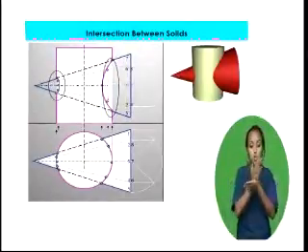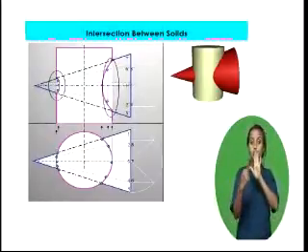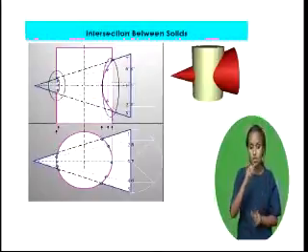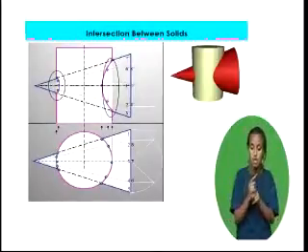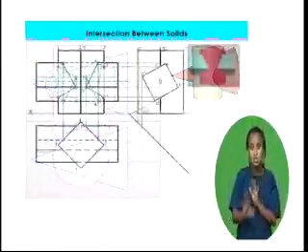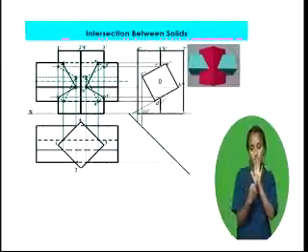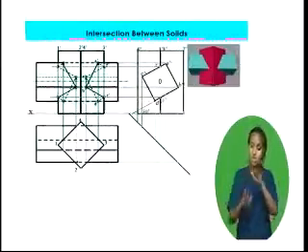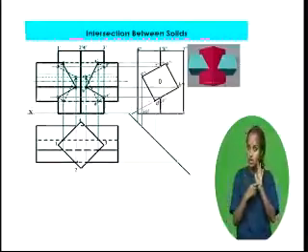On a sheet metal drawing, however, a sufficient number of points must be located to obtain an accurate line of intersection and an ultimately accurate development. The line of intersection of two surfaces is found by determining a number of points common to both surfaces and drawing a line or lines through these points in correct order.